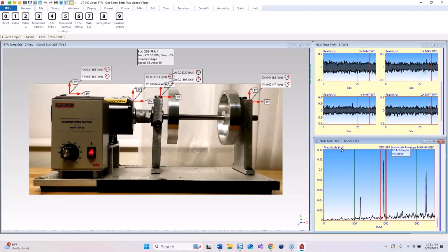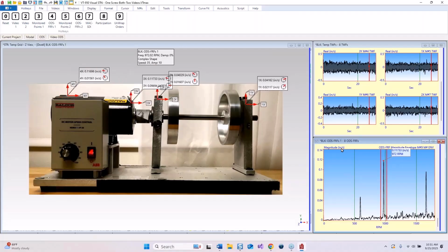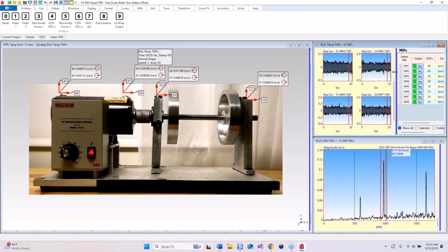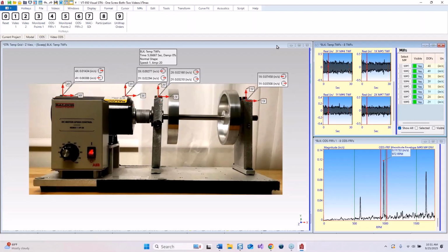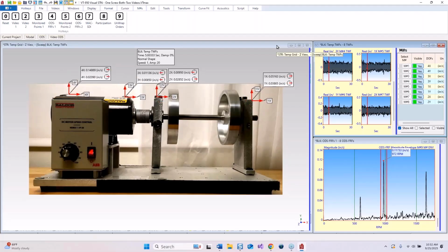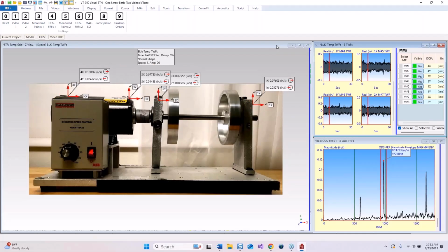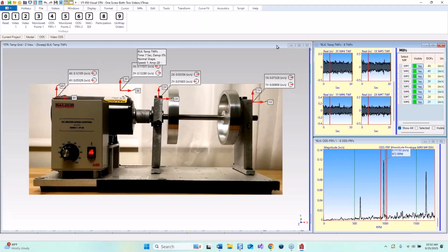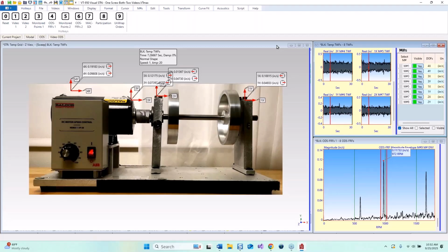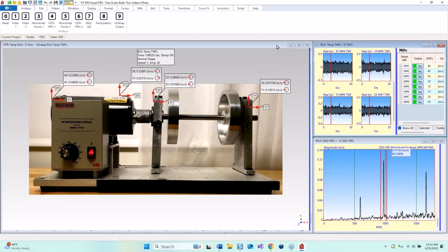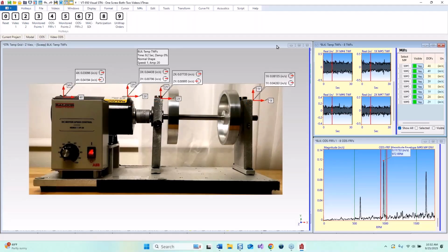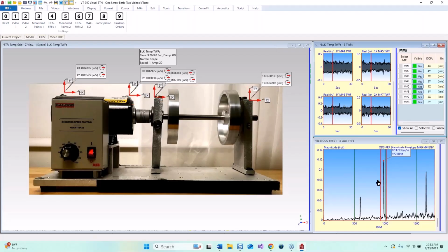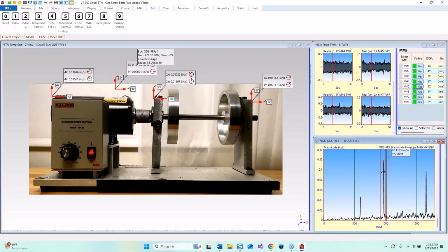So what we did is we took the displacement data, and here are the time waveforms from those 8 points up here, and we can animate them too. So now I got a sweep cursor going through where I can stop it anytime I want and put a dwell animation on, but that's a time-based ODS from those 8 points. Magnitude and phase, we're displaying that, and of course the phases are all just plus and minus, 0 and 180. Down here, I got different phases and different magnitudes,